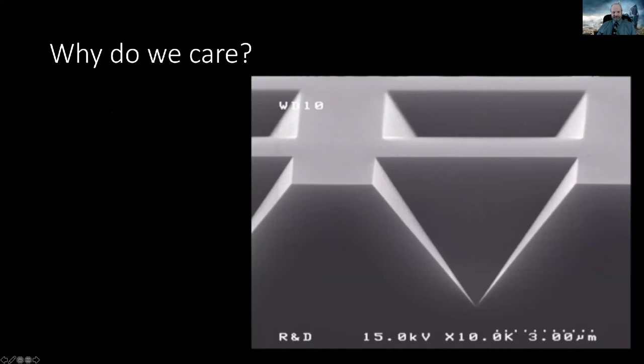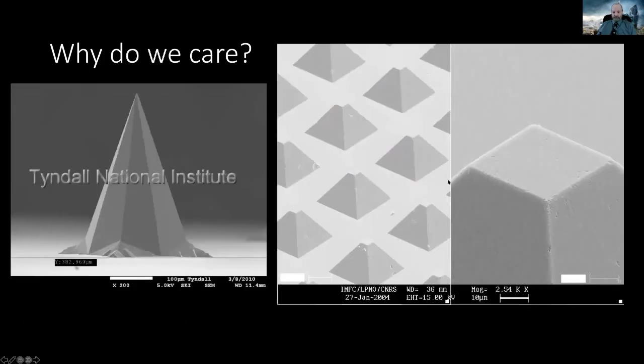All right. So here's some more pictures of what you can make in crystalline silicon, taking advantage of the crystal structure. So here the 111 planes actually etch down in the potassium hydroxide till they hit a point, and then they basically stop. So you can have a very well-defined depth, right, by defining the opening. Okay, you can also go the other way.